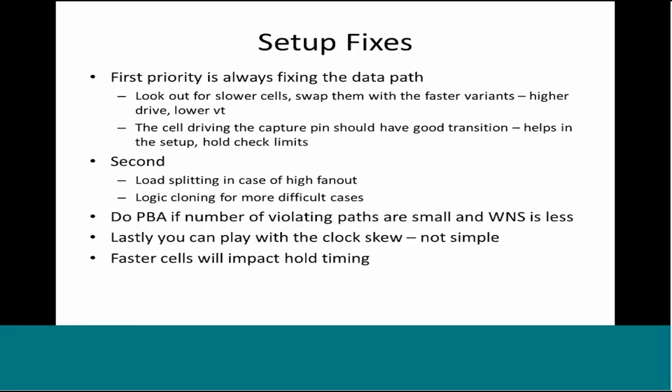Let's say if you make the launch clock earlier, it is going to affect the setup at this launch clock. If this launch clock has a critical path for setup ending at the data pin of this clock, making the launch clock earlier will affect the setup there. If you are delaying the capture clock, it will affect the hold there. So you have to check hold in the best case, check setup in the worst case on the launch clock, and so on. You have to do a lot of reporting before you attempt this. This is not a simple ECO even for the backend. The backend probably has to do some manual fixing here. So be careful if you are playing with the clock skew. It should be the last resort.